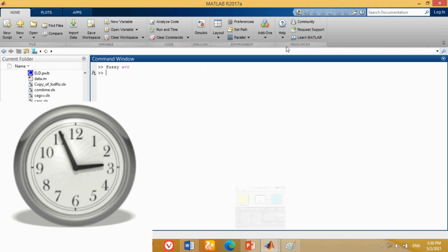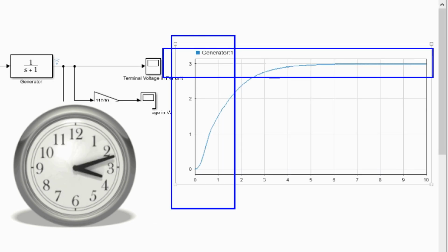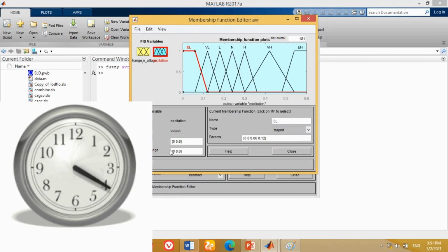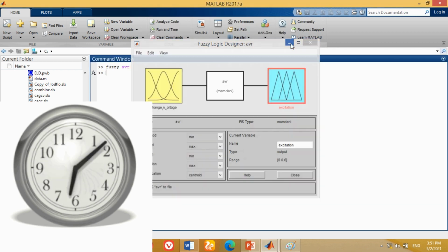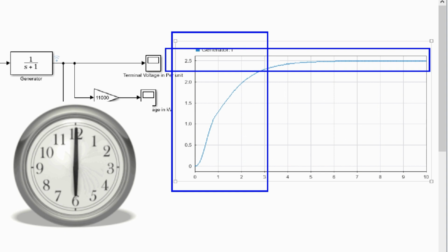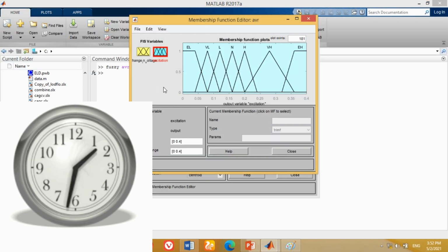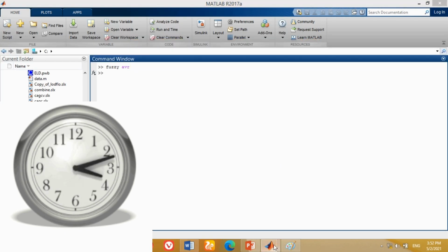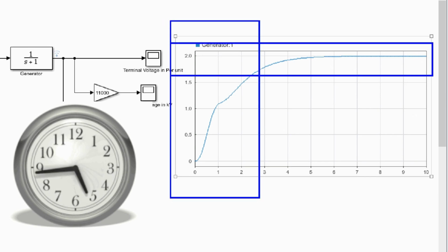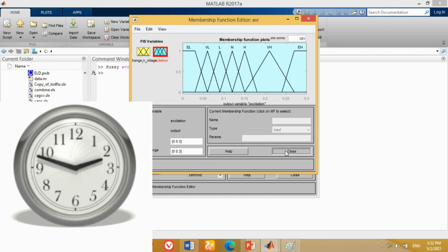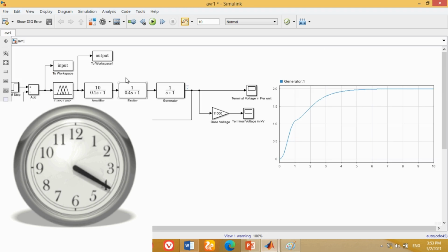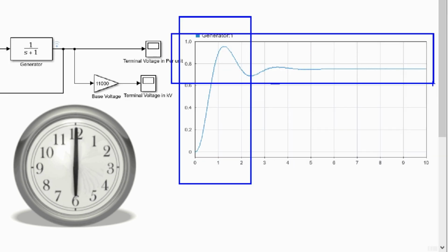Friends, now I think it is the best time to discuss the limitation of the fuzzy logic controller. Fuzzy logic controller has the limitation that it is not an expert system by itself. It needs an expert human to assign clearly all the correct rules in order to provide the best response. If the expert gives wrong rules, then fuzzy logic controller may provide poorer performance than even the PID controller.